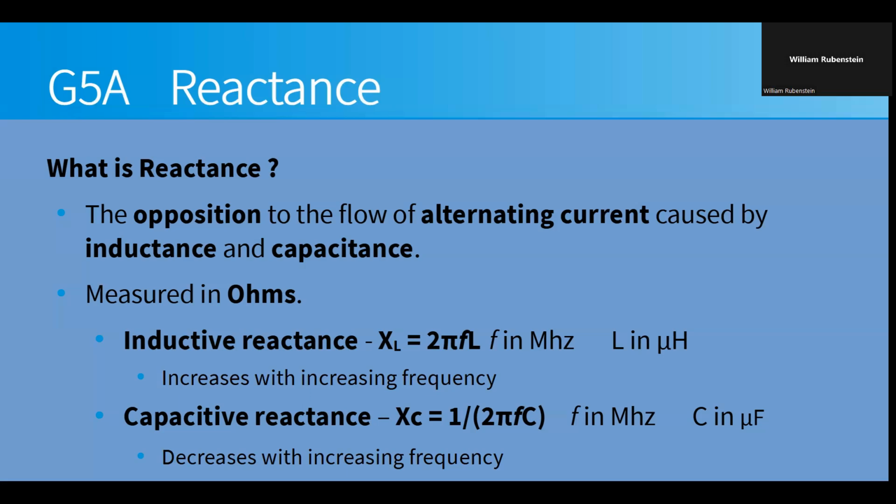Same with capacitive reactance. The difference is it's 1 over 2 pi times the frequency times the capacitance. So it's a reciprocal function, and it's nonlinear. The main thing to remember, and it is a test question, is that inductive reactance increases with increasing frequency. Capacitive reactance decreases with increasing frequency.